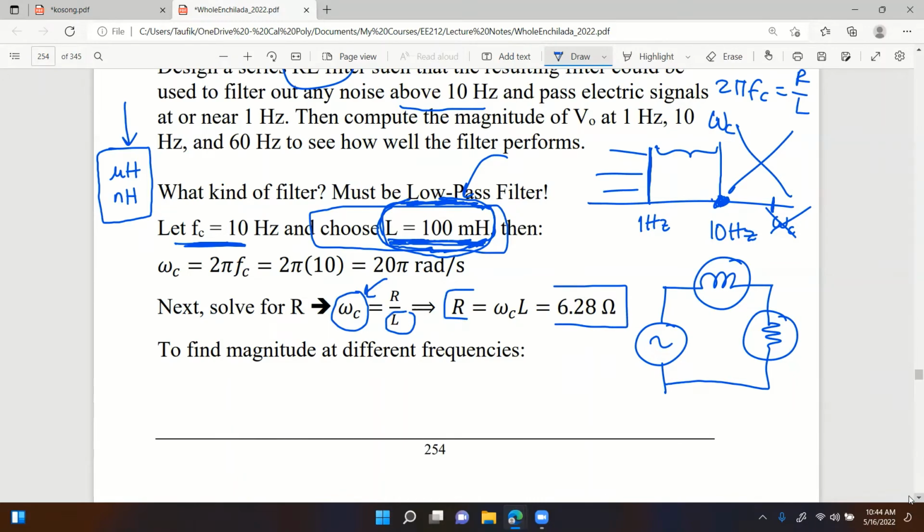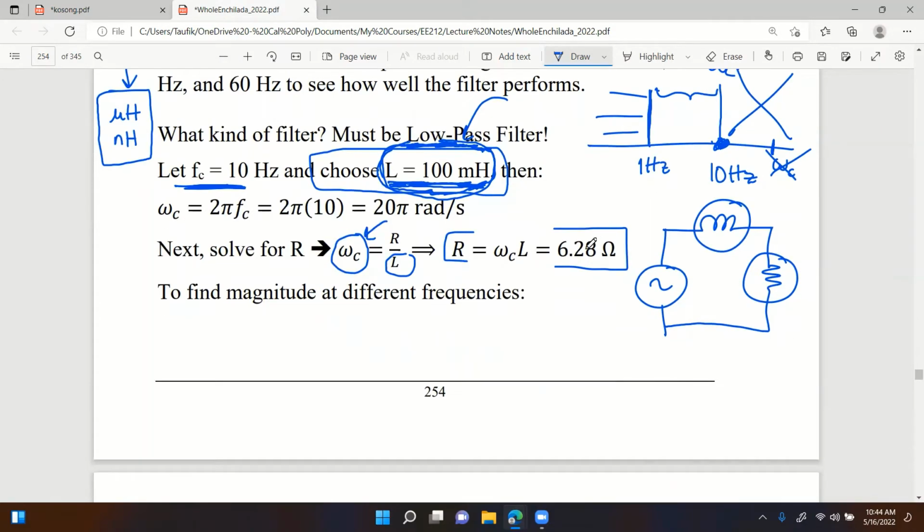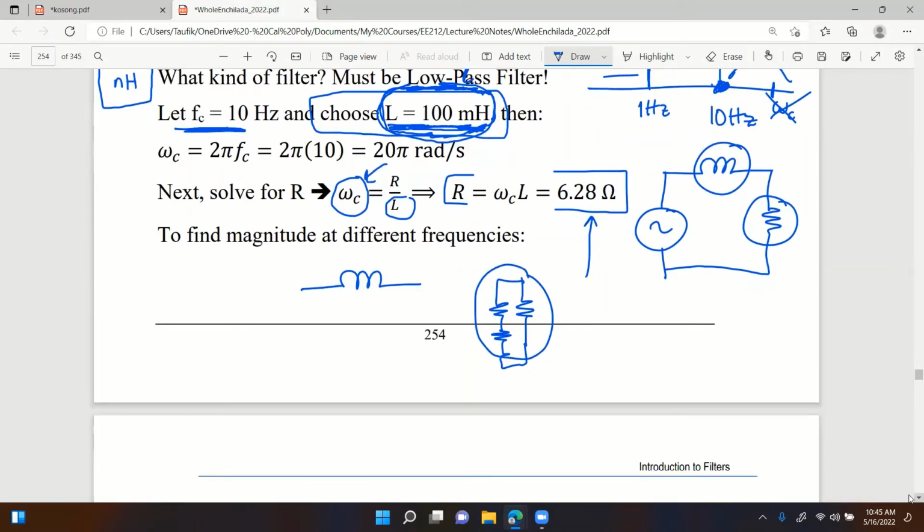If this is the actual design, this is still a concern because this is not a standard, commercially available value of resistor. But at least for resistors, you can always do combinations of series, parallel, and so on. You don't want to do that for inductors, trust me, because they're expensive and bulky, so you want to use only one single inductor. With a resistor, you can do all kinds of combinations to get the actual value, and they're small. Any questions?